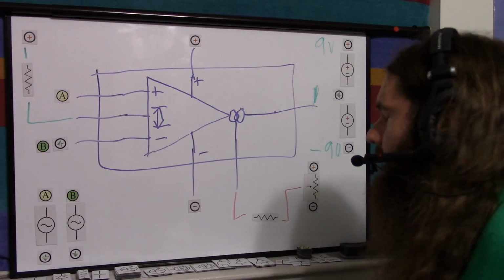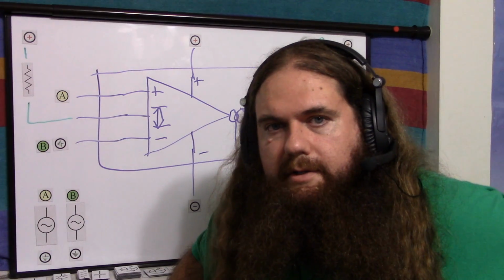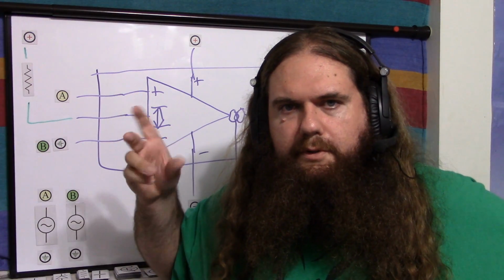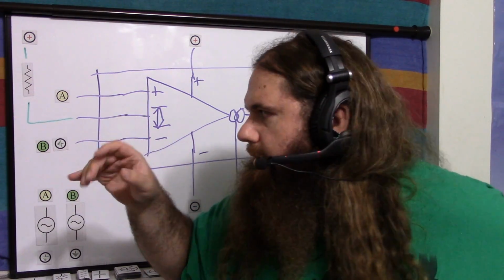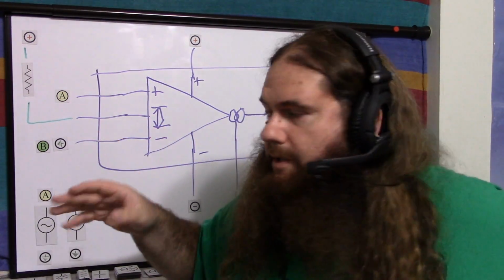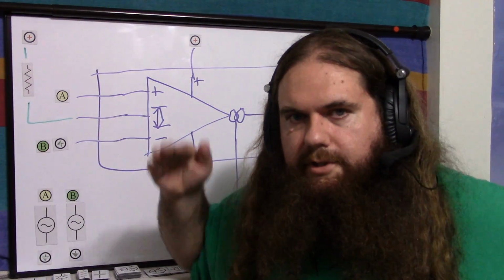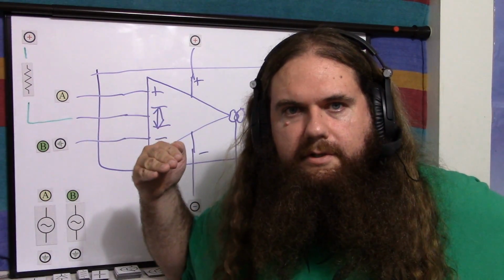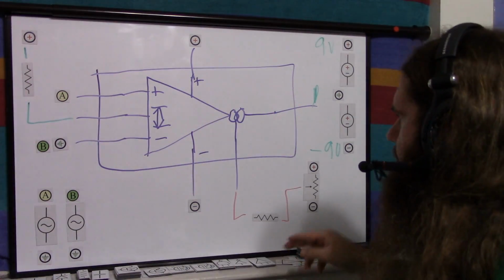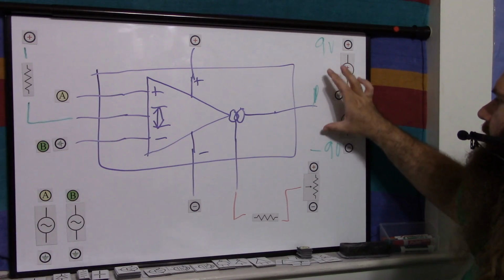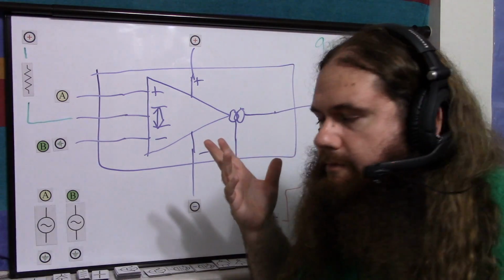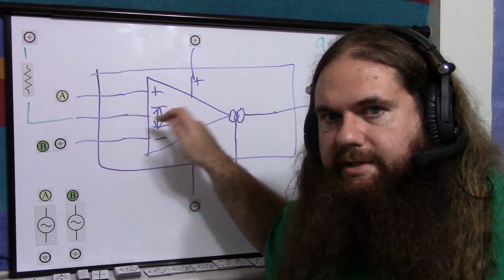Positive and negative power. And you can use it single supply, but why? Single supply op-amps are much more useful. You're doing logic and comparators and other things. I'm sure I will eventually come across a useful single supply OTA, but we're processing audio signals, which you should be doing with positive and negative voltage, so there's no DC bias. So let's just assume you're using negative power. So positive and negative power, just like so. Make sure they're the same value, plus or minus 9, plus or minus 12, plus or minus 15, whatever, so that this thing gets the right 0.